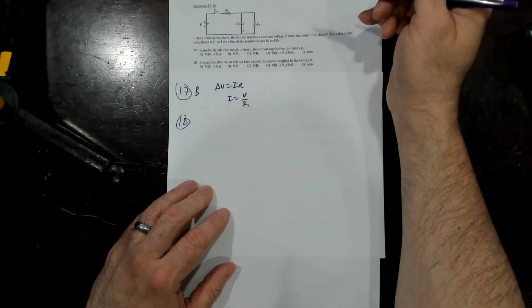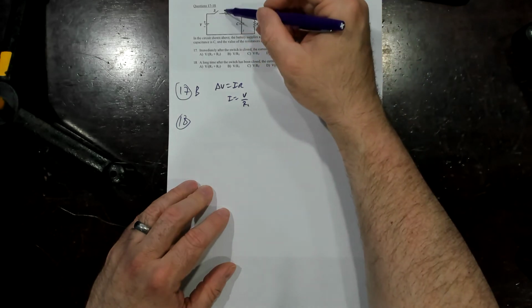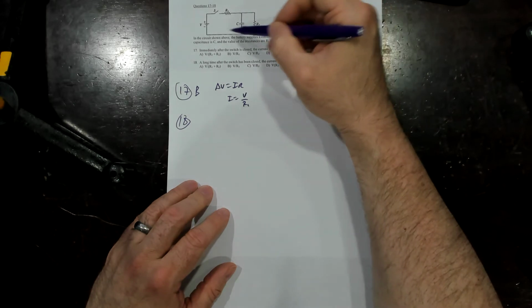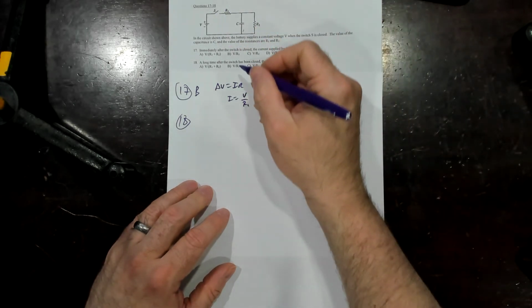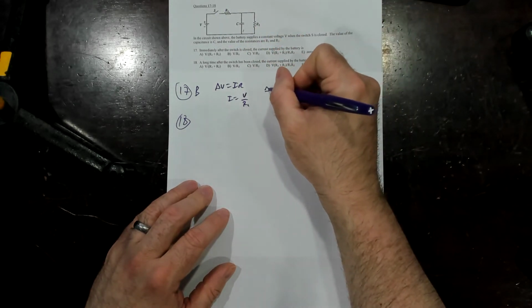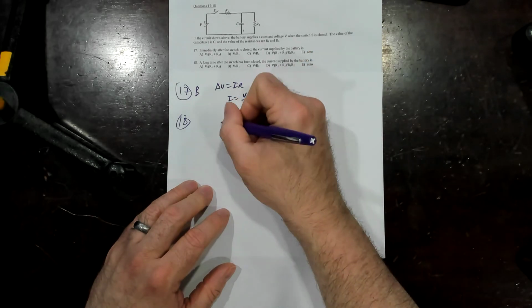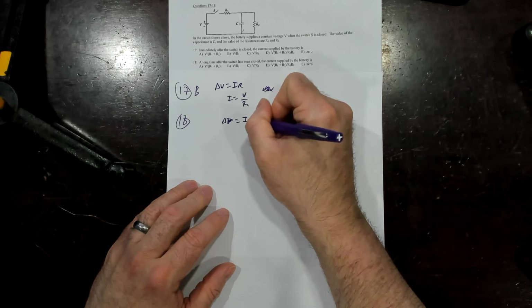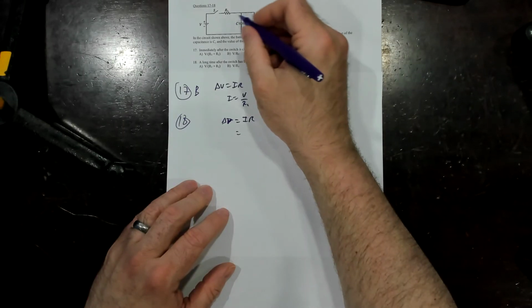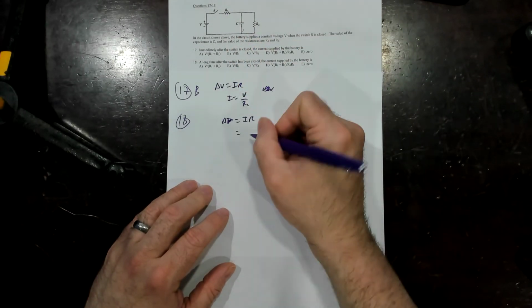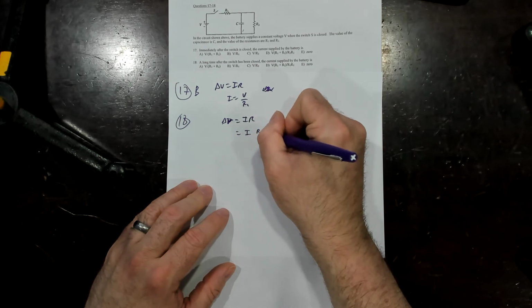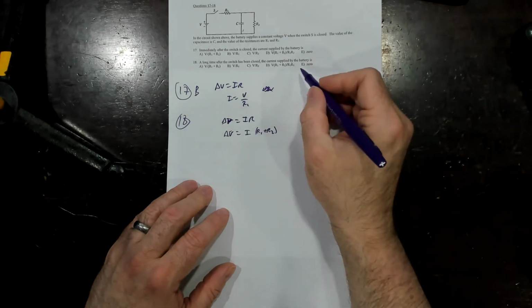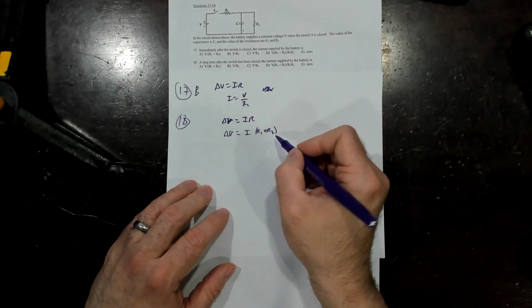And so I'm going to go down R1 and then down R2. I've got 2 voltage drops. Delta V is IR, but my R is now both these guys in series, one and then the next. So it's my I times R1 plus R2 that is my delta V. And I'm trying to find the current, so it's just going to be delta V over R1 plus R2.